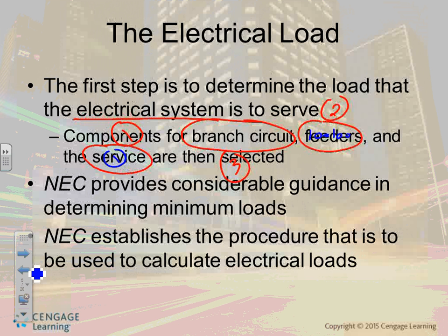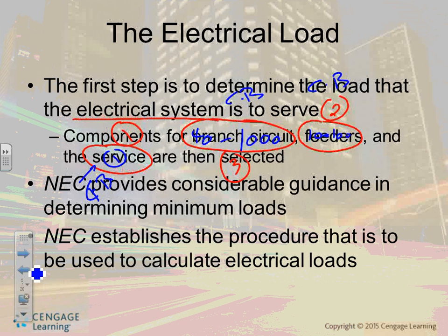Now, for branch circuits here, guys, in a typical building you can go from 40 all the way to 1,000 branch circuits. These are all the little circuit breakers in the panels, and a little bit bigger for all the mechanical equipment, the heating, the cooling, the lights, and the receptacles. Am I making sense? All of them must start with a circuit breaker. Ahead of every one of these, you need a circuit breaker or a fuse, and a service has to land on a circuit breaker or a fuse. And then you pull your conductors. Does it make sense? So that's basically what the load calculation will get you.